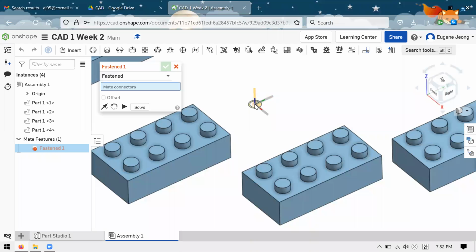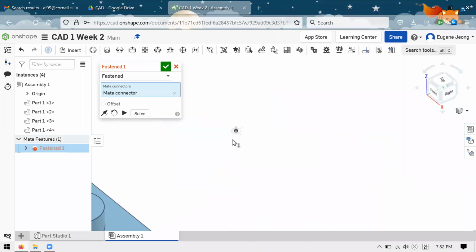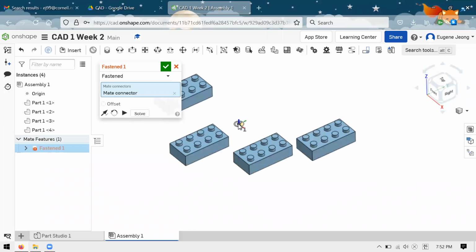Let's say I just want to face up. So if I put my cursor first over the point, the origin, and then I move it up a bit, I'll have the connector that I want. Once I have a shape that looks like this with that little circle pointing up, I click once, and you can see this faint outline of what's happening.